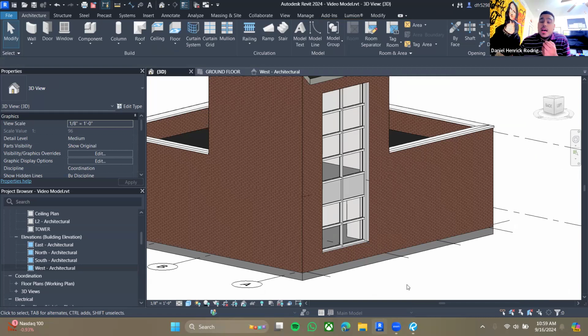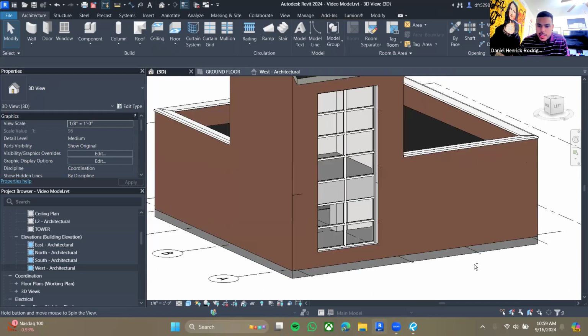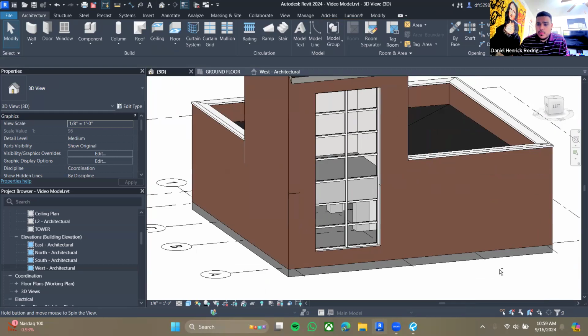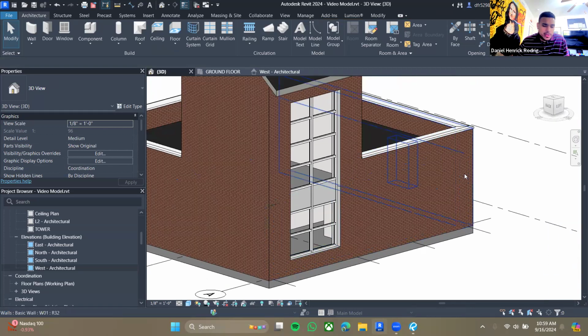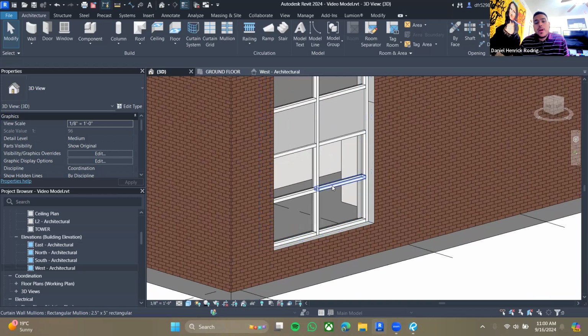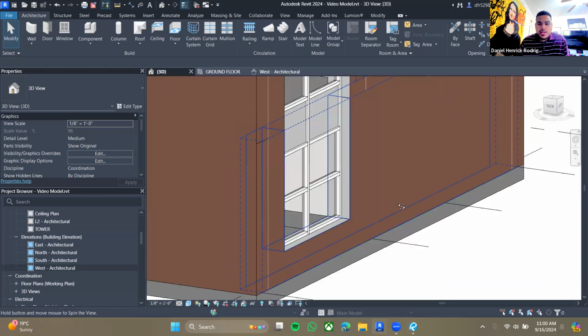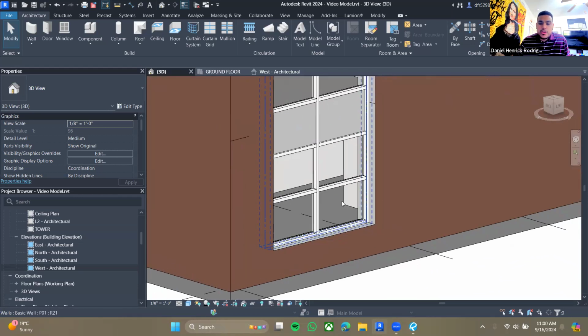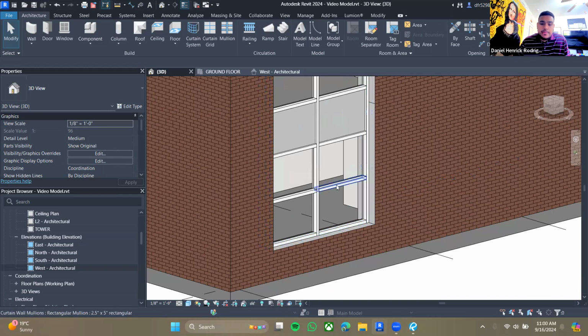I realized that one thing that I don't teach you in this project is a door within a curtain wall. So I'm just going to quickly show you that. You don't have to follow along. Well, you don't have to do it, but please follow along because this will be useful for Steam services. But I just wanted to let you know that if you're creating a door, and I'm just going to put a double door here, and it's going to look wonky because it's not the right dimensions, but it's just to teach you how to put a curtain wall in place in the first place, okay?